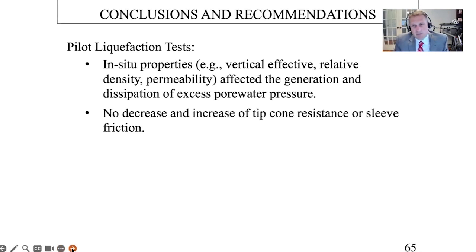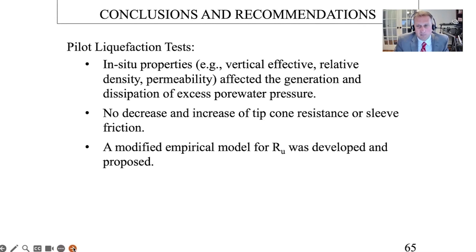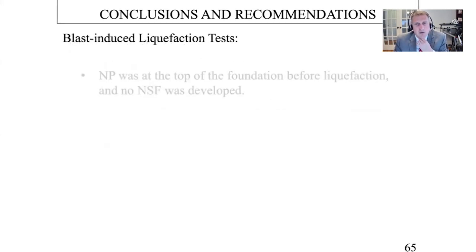Okay, so it's just some conclusions and recommendations that we have out of this. The in situ properties were affected by the dissipation of excess pore water pressure. There's no decrease or increase in friction caused by the blasting, and so we could reblast if we wanted to do more tests than just one. A modified empirical approach for RE was developed and proposed, and so if you're going to do some blasting, that's a good modification that we put out into a journal article.